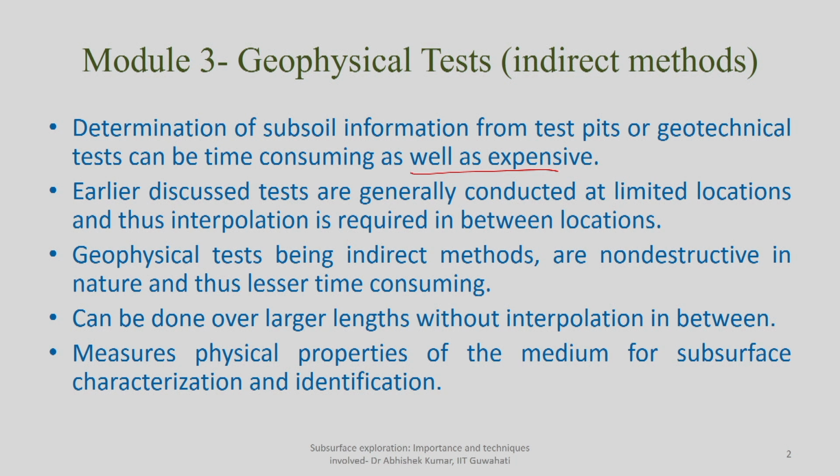So, that is another important aspect when we go for geophysical investigation, like those are less time consuming as in comparison to geotechnical test, and interpolation is also significantly easier. Rather than going for interpolation between two test locations which are wide apart, you can go for more number of tests, because these are relatively quicker methods. So, geophysical test being an indirect method, because you are not getting any kind of soil sample from the depth, or you are not taking out the sample, or any kind of sensor you are not going to lower there.